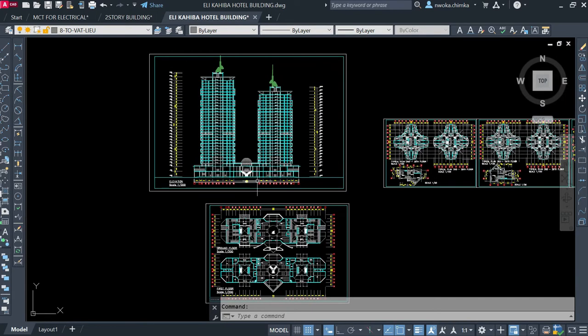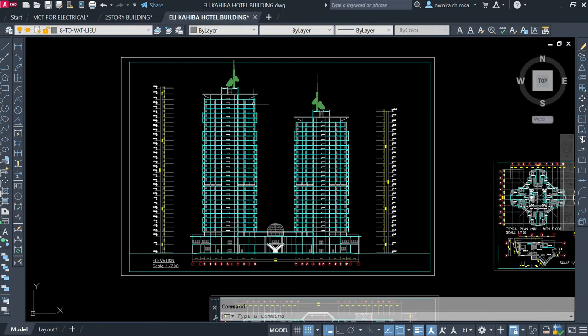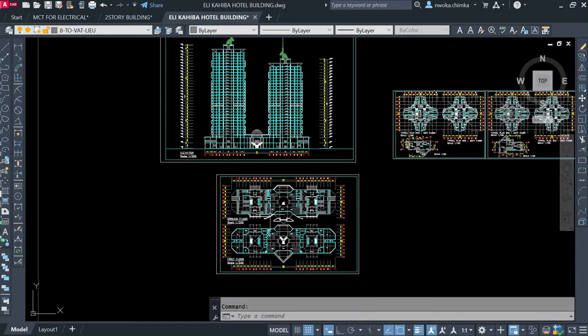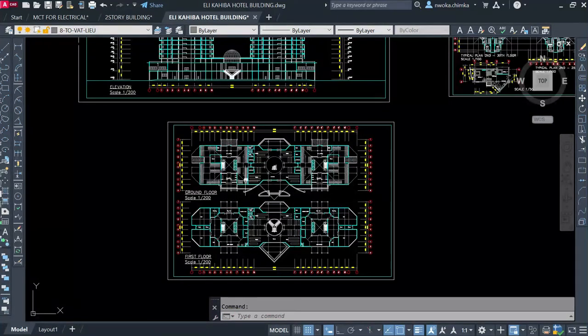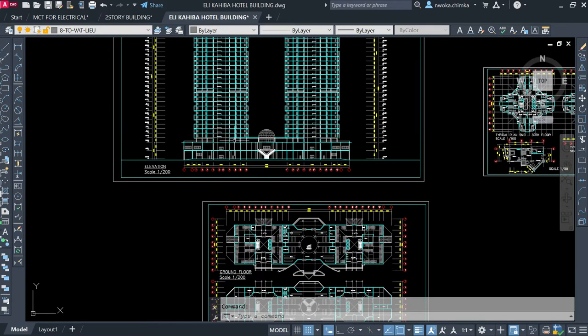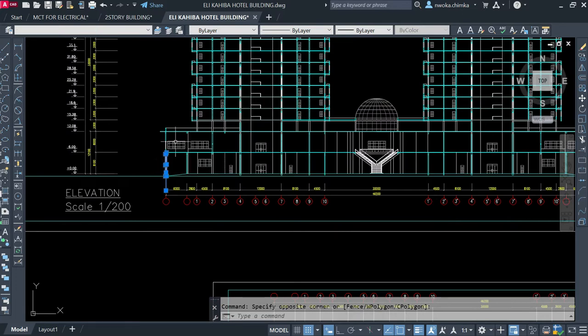Now, when we got this plan, this question came to our mind, and we used at least 15 minutes to study the building very, very well. We then came to a conclusion that we will not put our column position on this first floor or second floor plan, because if you export this to Prota Structure, you will only be able to model just the ground floor and first floor.